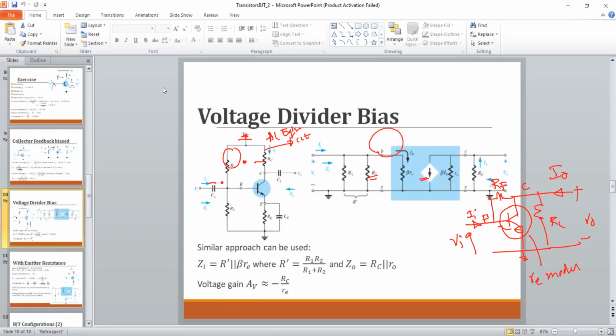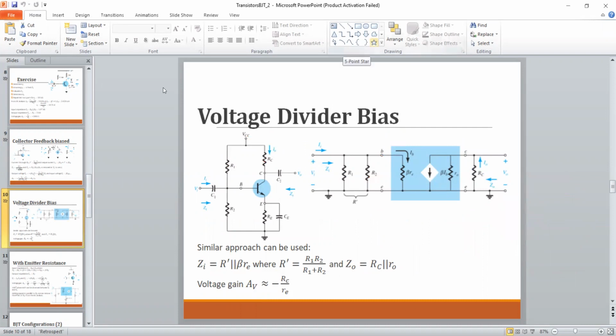So then we'll discuss one more. This is voltage divider bias. How do you map it to the AC equivalent circuit? Set this to 0, so this becomes grounded, and this is short, this is short, and this is short. Due to this replacement, there won't be any impact from RE to the circuit.